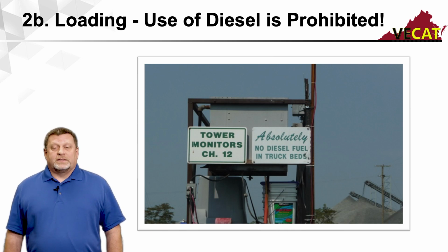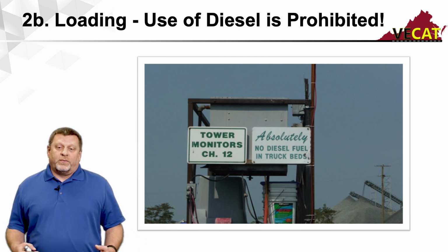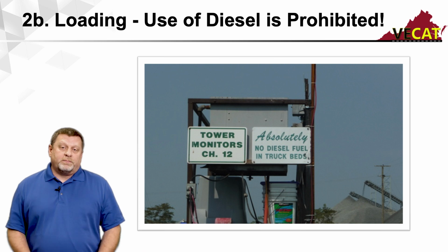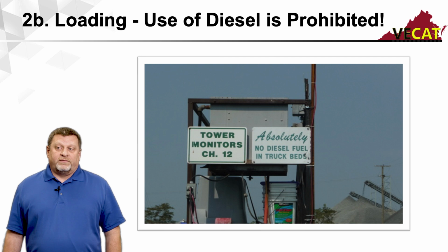Diesel fuel is absolutely prohibited. Diesel fuel will break down the asphalt binder in the mix. It will keep anything from sticking to your truck, but at the same time, it's going to react with the asphalt mix that's going to be placed, and it will significantly do damage to the product. So diesel's not allowed to be used in truck beds. It's not allowed to be used on a job site. And so there's really no reason to have diesel on the job sites at all anymore.